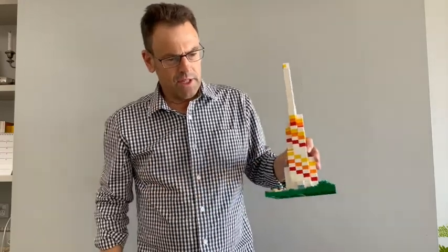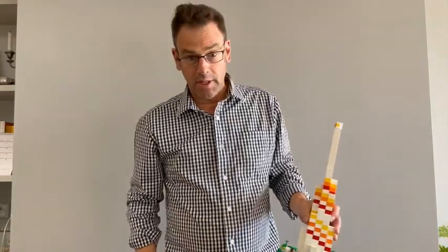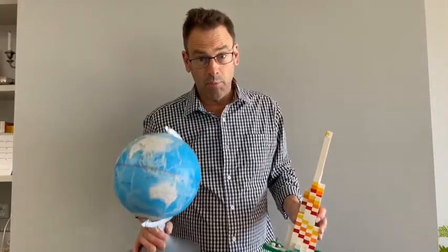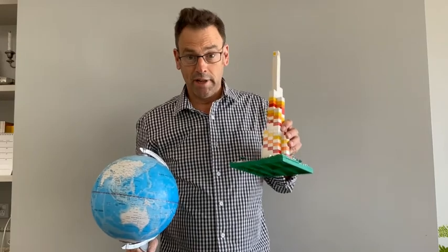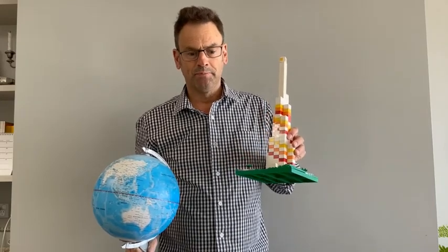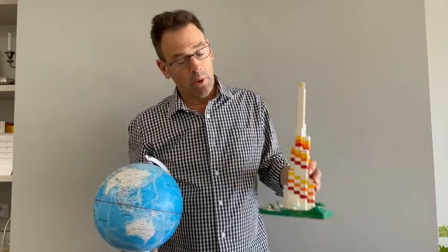Now, there's many different attempts over the years to mathematically take a round Earth and put it into a flat, regular XYZ system. Now, the most common one we use is one called transverse Mercator. And what that does is strip the world into slices and make each of those slices flat. Now, rather than pull apart my son's globe, I will take a smaller